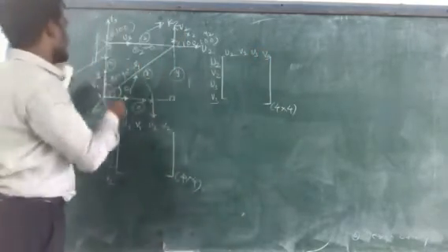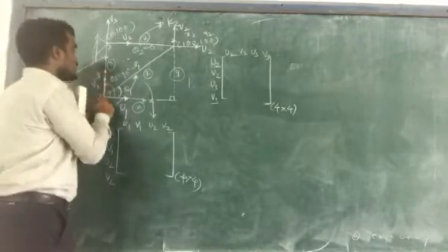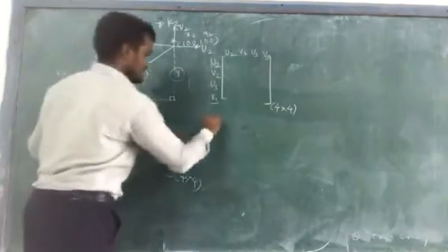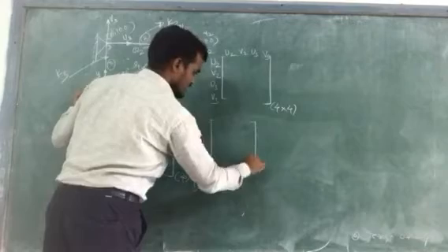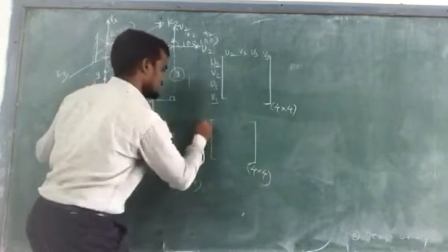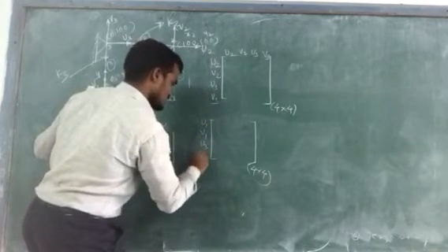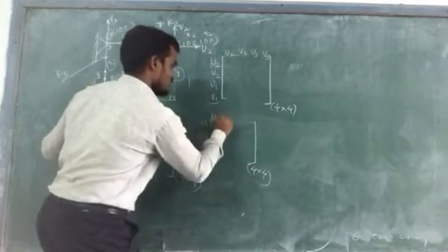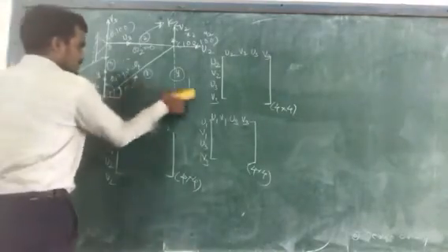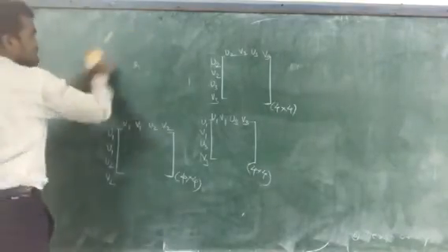Then the connectivity for the third one is between node 1 and node 3, so it will become u1 v1 u3 v3. We simplify, and we will get this third 4x4 matrix. Then the connectivity should be u1 v1 u3 v3. Now we need to add these 3 matrices globally,